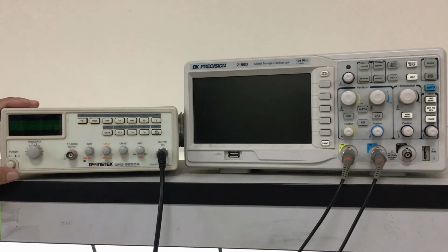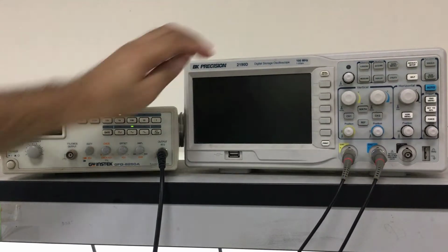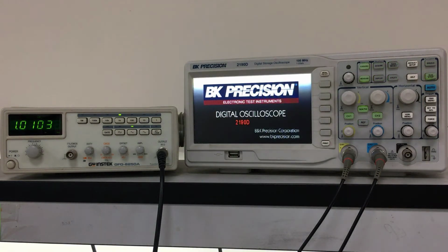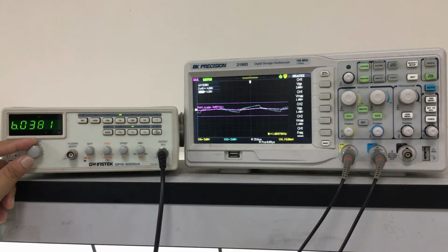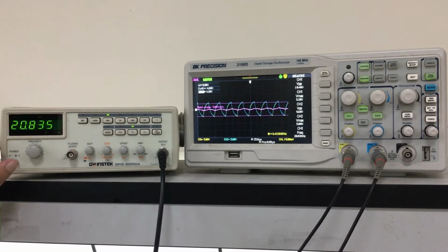Now I turn on the function generator by pressing this button, and the oscilloscope by pressing this button on top. Our required voltage settings is 10 kilohertz, 3 volt peak. So at first I adjust the function generator to give us 10 kilohertz. If I reach the max position, we will not be able to get to 10 kilohertz. So I reduce the frequency knob, change the range to 10k, and now I can adjust it to 10 kilohertz.